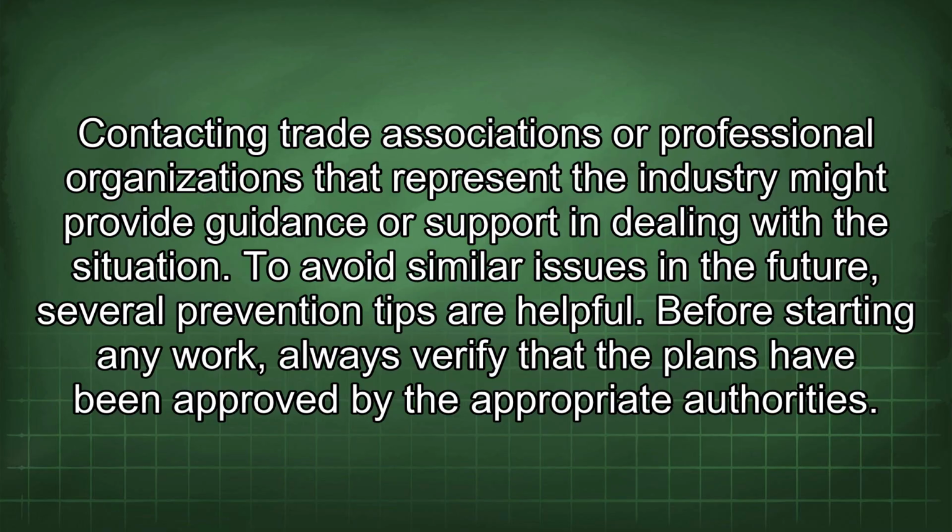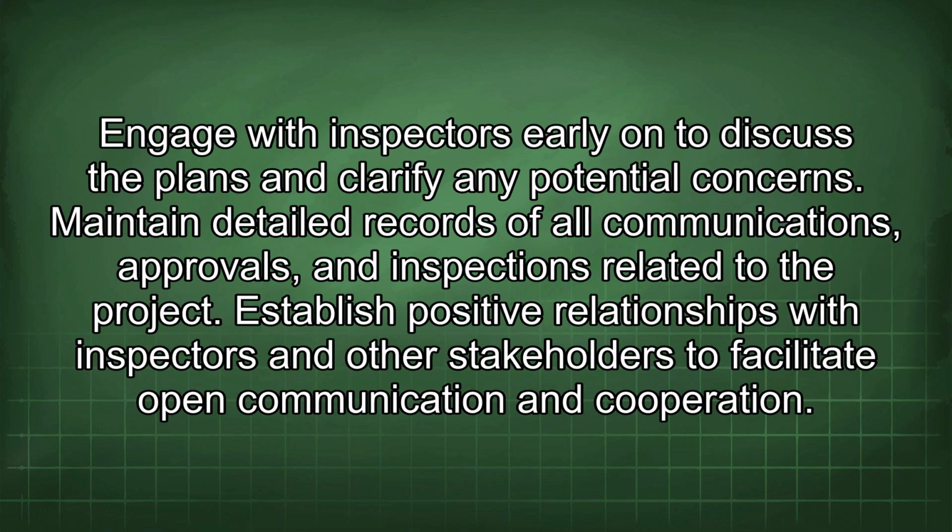To avoid similar issues in the future, several prevention tips are helpful. Before starting any work, always verify that the plans have been approved by the appropriate authorities. Engage with inspectors early on to discuss the plans and clarify any potential concerns. Maintain detailed records of all communications, approvals, and inspections related to the project. Establish positive relationships with inspectors and other stakeholders to facilitate open communication and cooperation.